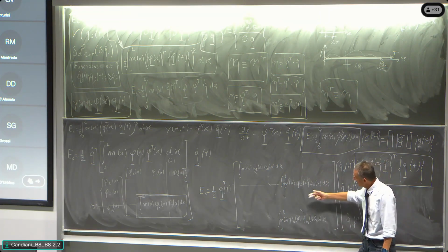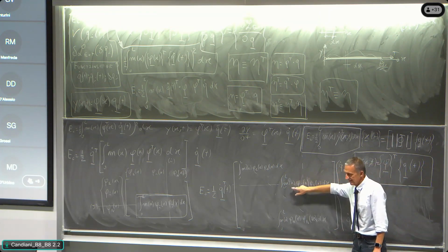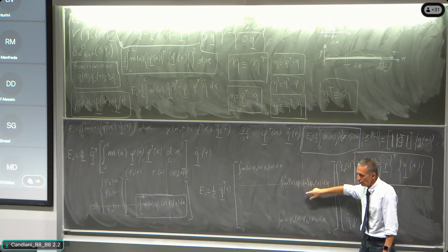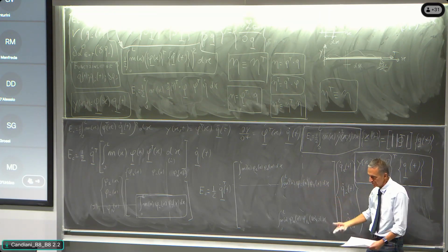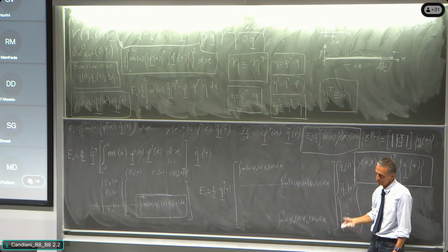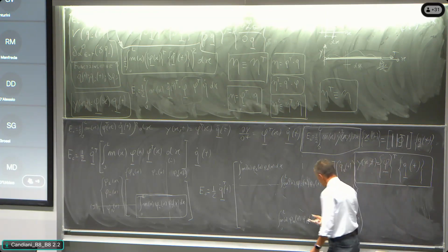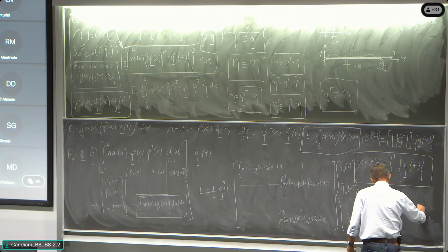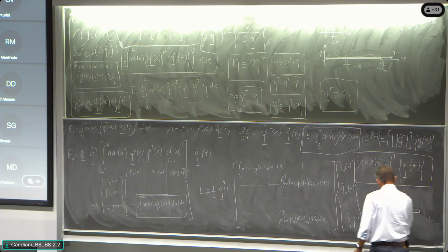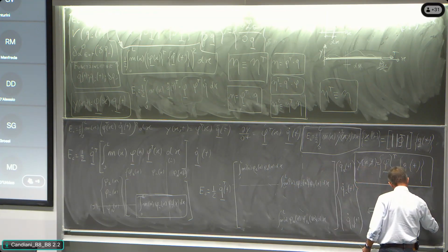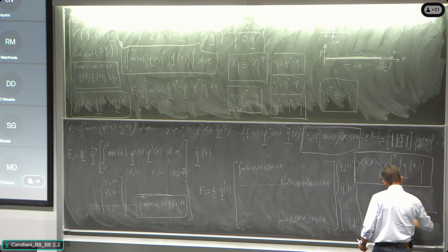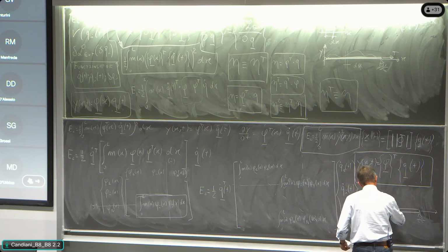So the orthogonality is that the modal shapes weighted by the mass distribution give a cross product integral equal to 0. Of course, take the modal shape of a very simple beam or a tensioned cable, which we are pulling here, and the first mode is this one, the second mode is that one.